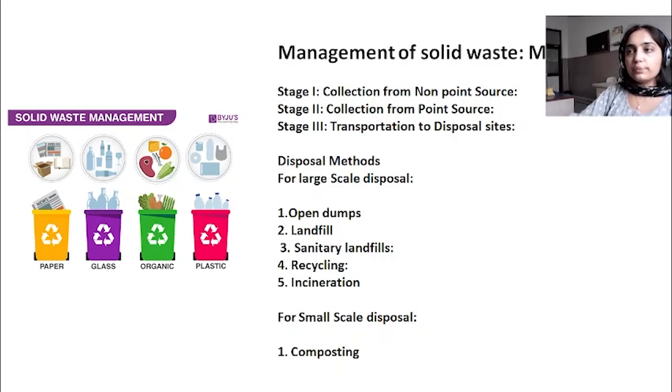Next is landfill. Landfill is burying the garbage, which involves disposing of waste in a landfill, and most nations still follow this standard procedure. Landfills are typically found in urban locations where a lot of garbage is generated and needs to be disposed of away from public space. The operational equipment is reasonably priced and is versatile enough to be used in various other municipal activities. This approach avoids the serious health risks to the community posed by open dumping or burning. Landfills are frequently built in borrow pits, mining voids, and abandoned or underutilized quarries.